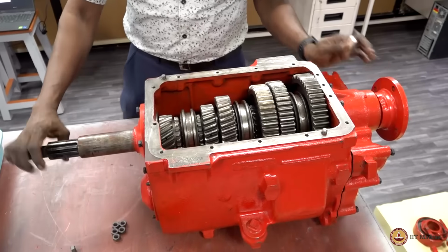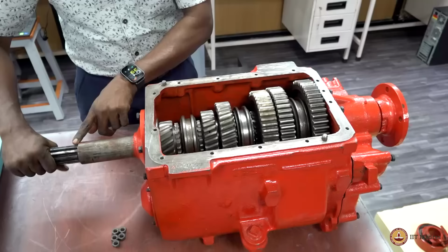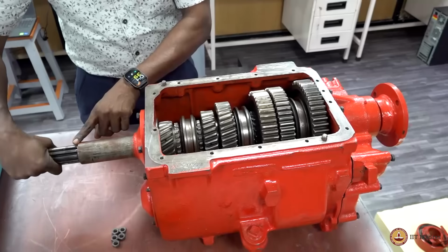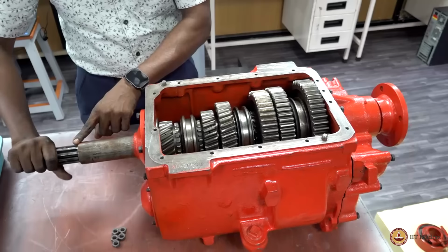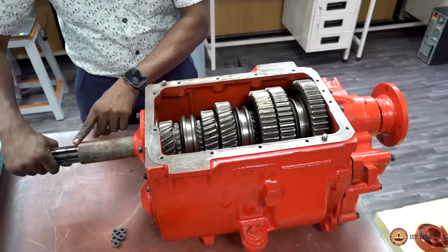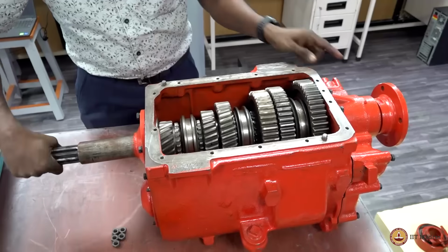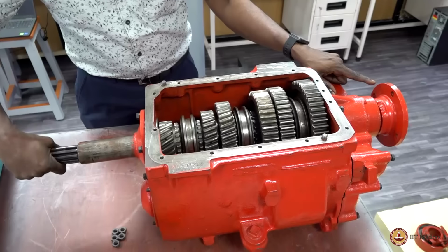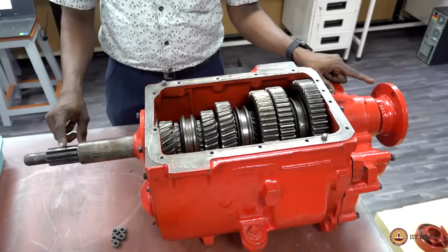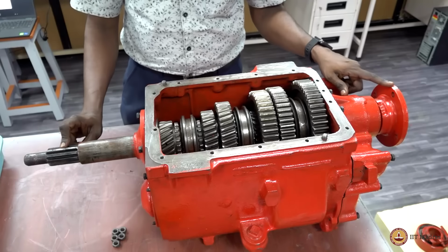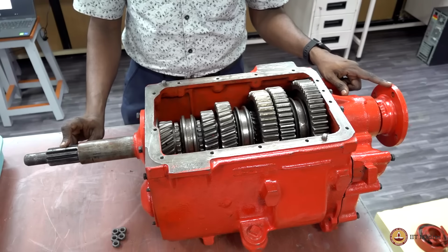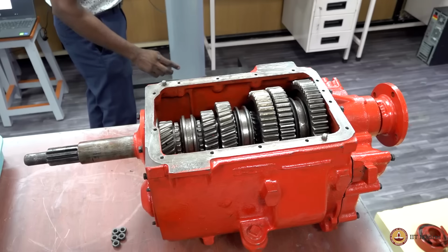Now, one, two, three, 4, 5, 6. Now the input shaft has completed 7 complete revolutions. As you see here, the flange has completed 1 complete revolution, meaning our calculations are correct for the first gear